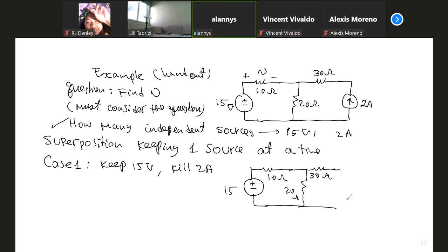I'm not sure. Why? We are way into circuit analysis. I think I'm just confused on what you're trying to ask me. I'm turning off the current source. Current source is not generating current. It generates zero current. So in my circuit, how do I show that? I did ask a question in exam. Exam 1. Did you see the solution in exam 1? I asked you to kill sources. Didn't I mention how to kill voltage source, how to kill a current source? Don't you just have nothing there?